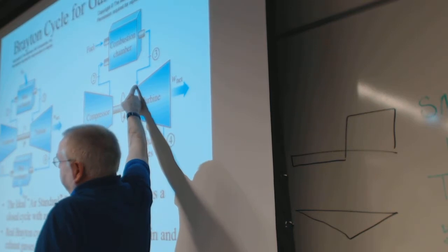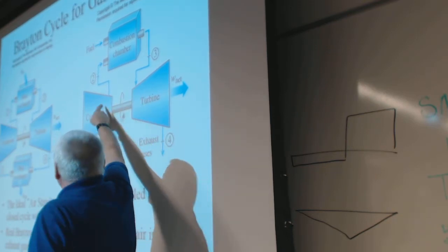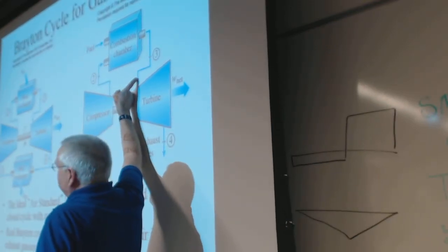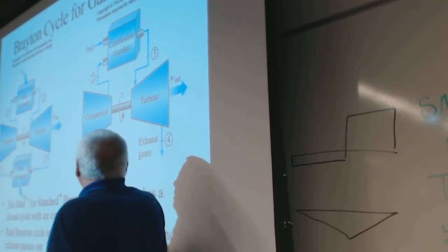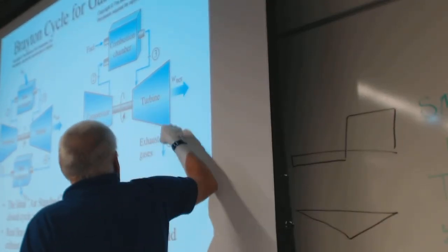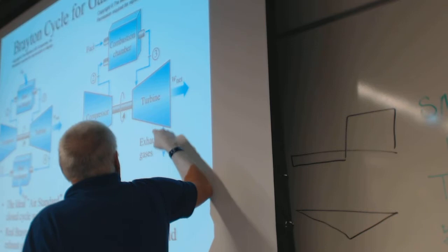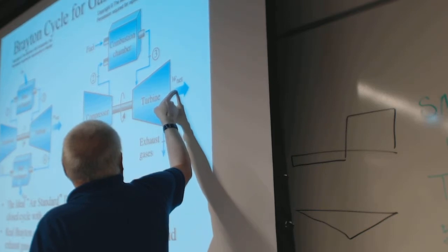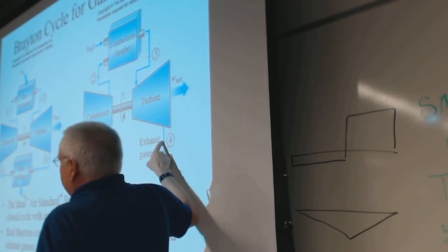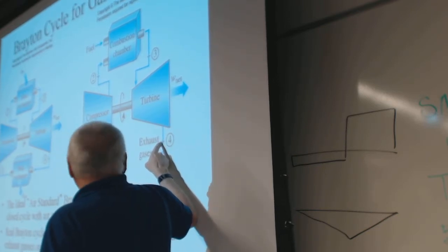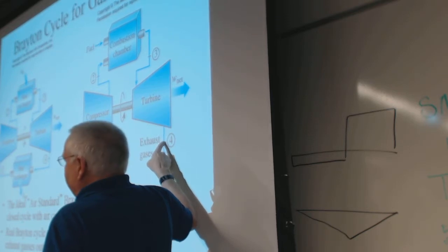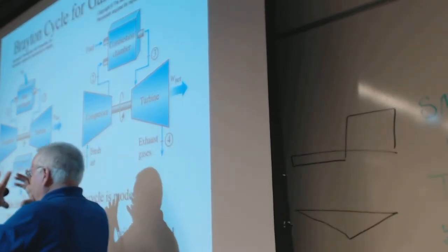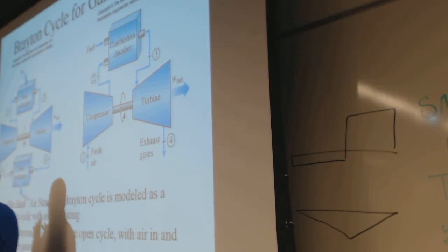And then it comes to the turbine at high temperature, high pressure. It's got high temperature and now it wants to expand a bunch. As it expands through the turbine and back down to the low pressure, it generates work. Now, if you make this net work go to zero, then the temperature it comes out at is going to be high, and if you force it through a small nozzle, it goes fast.